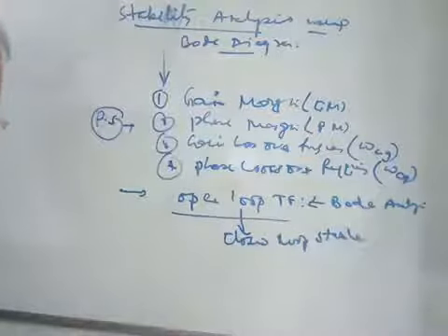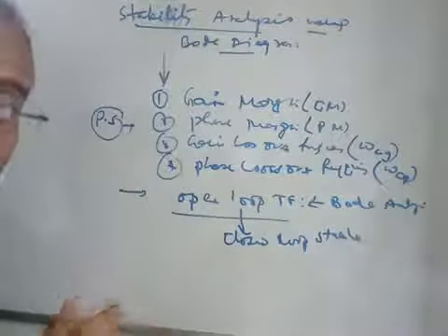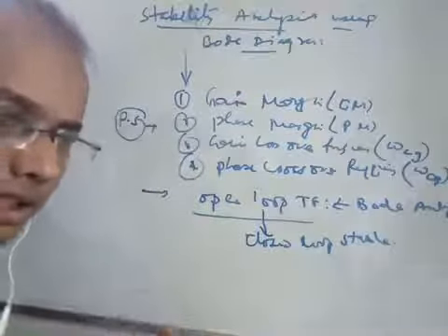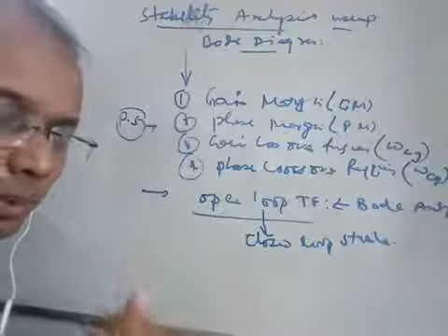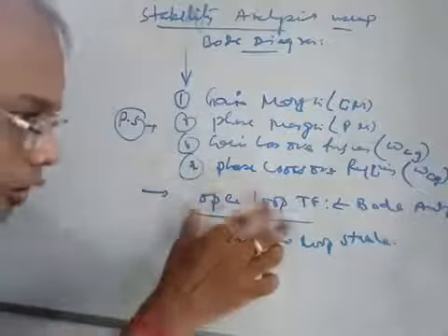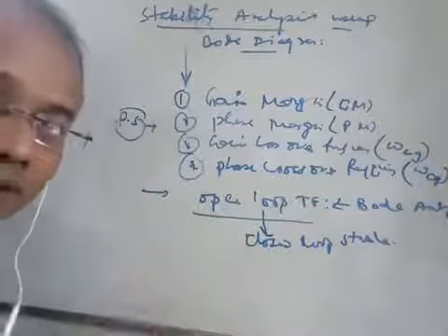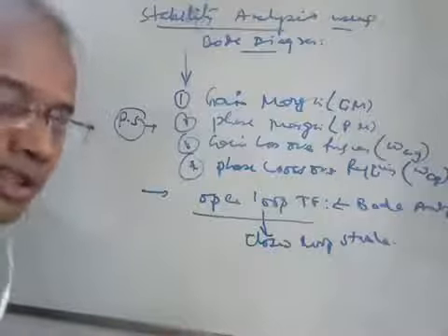The beauty of the frequency domain analysis method, that means analysis of the stability using the Bode diagram, or the polar plot or Nyquist plot also, is that the open loop transfer function is considered for analysis, but at the conclusion you can say whether the system is closed loop stable or not, right?